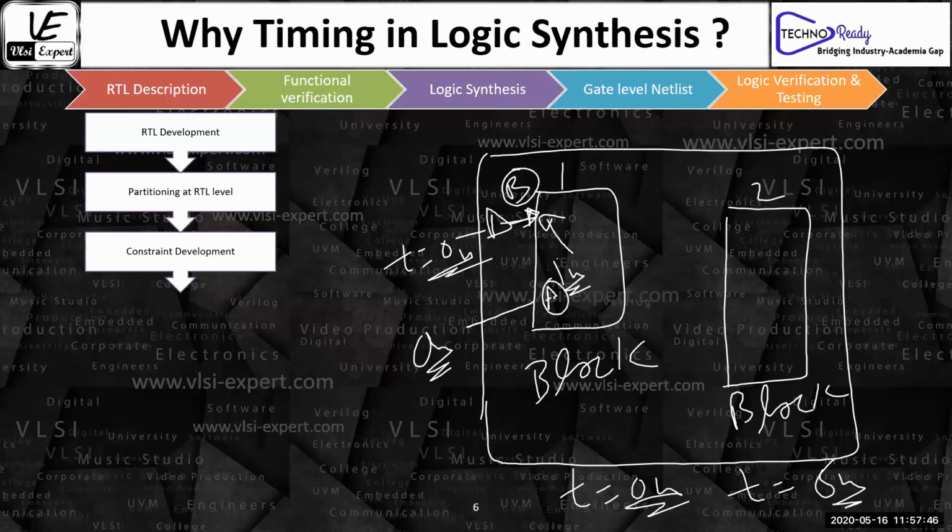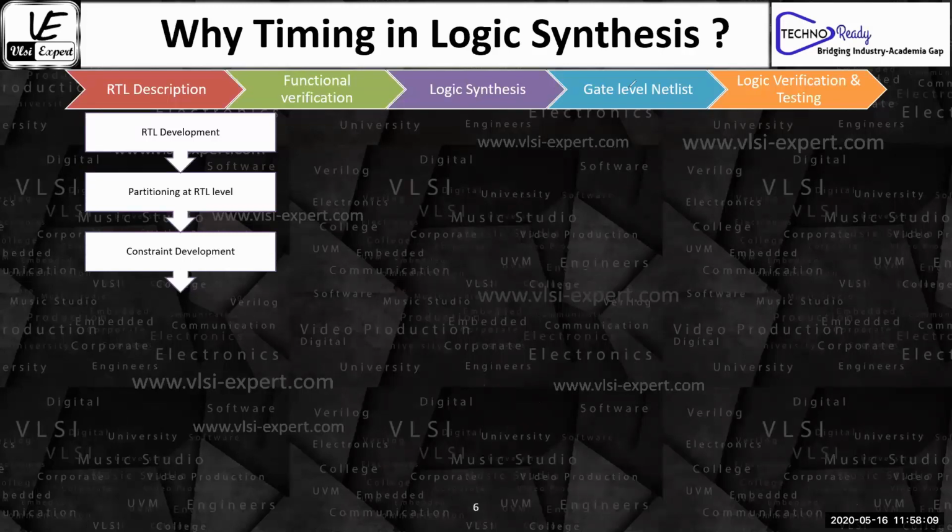These constraints are something very important whenever you're doing the partitioning or block level, and that's the reason it's mentioned here. The moment you divide your RTL, or do the partitioning of your RTL, you have to develop constraints also. That's important from the front end engineer's point of view. It's not only about writing the RTLs; it is also important to write the constraints, at least for your block.